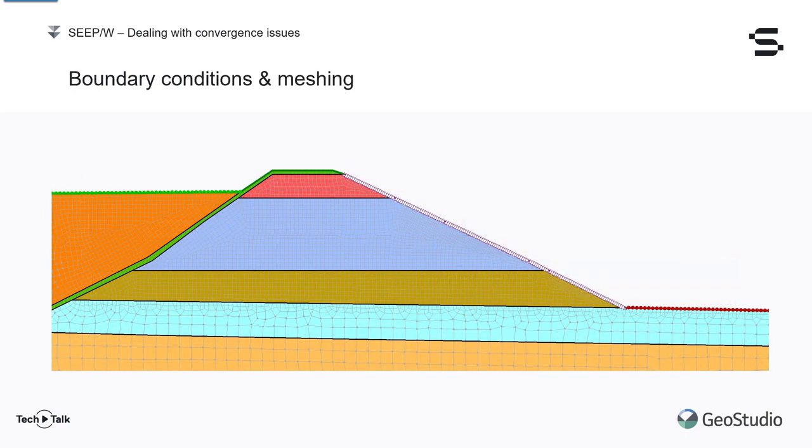There are three types of boundary conditions used. On the upstream side of the dam, a total head boundary condition is used to simulate the measured elevation of the water table. Having the boundary condition applied to the top of the tailings deposit instead of the far-field left side edge of the geometry is a bit unusual. I have chosen to apply it this way to better represent how tailing materials are deposited fully saturated on the underlying materials, which decreases the depth of the water table, even very close to the dam.